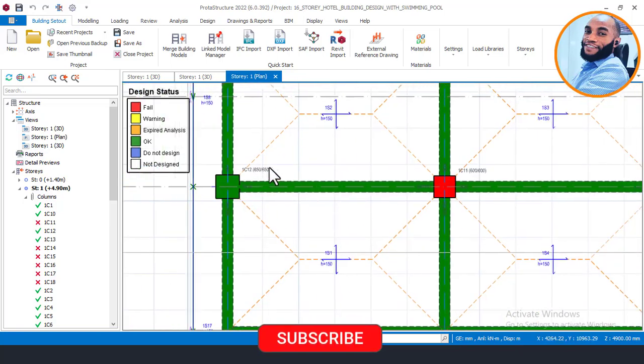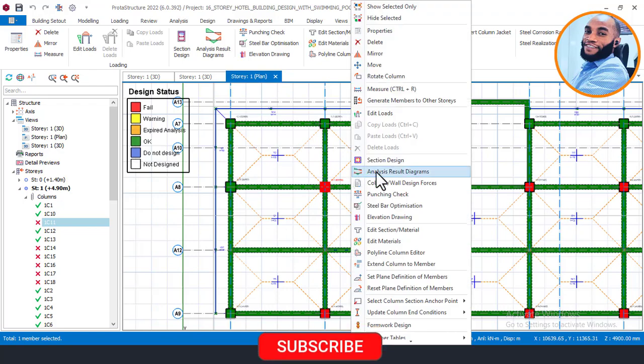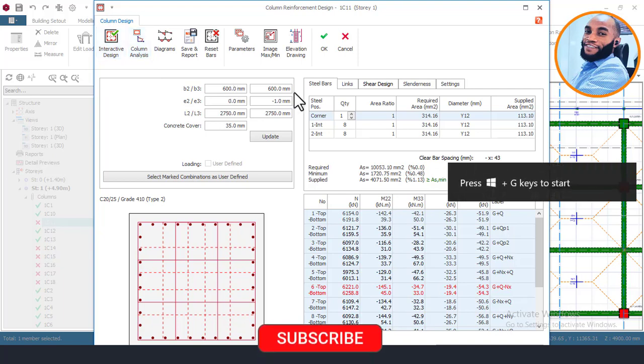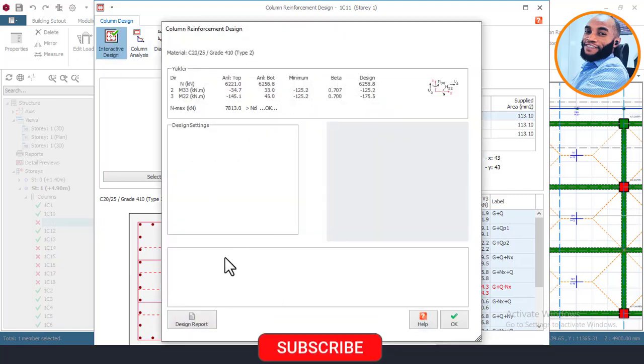So with this idea, I'll go again and check for this other one too by clicking on the column here, and then clicking here and then section design, and I'll hold on again for it to show. I'll not just go and increase the size first. First of all, look at what is causing the failure. So always click on this place first, design, and then wait for it to show the warning.